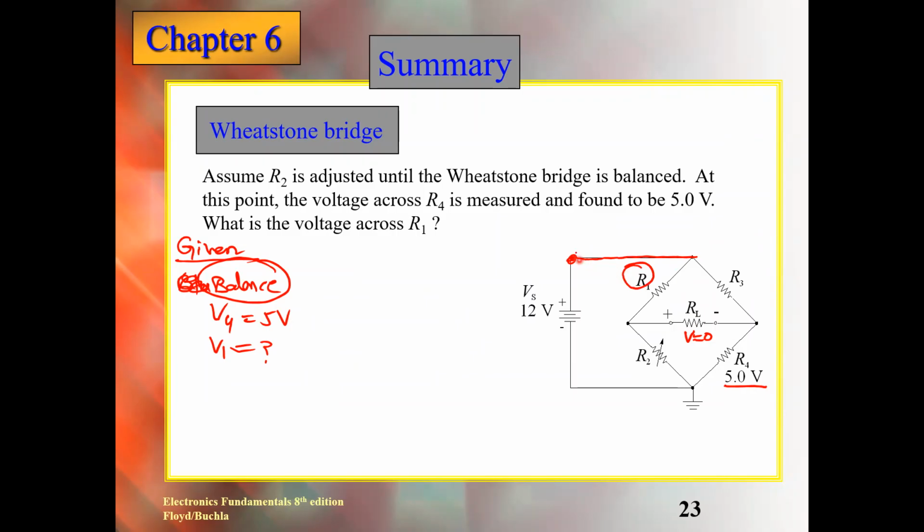So we can start from here. We can choose this path, go this way, come this way, and complete the closed path. While we are traveling this way, we can calculate the voltages. As we travel this way, this is V1. This is VL, which is equal to 0. I am writing here, this is V4.